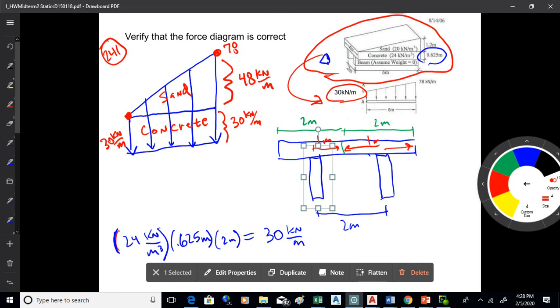I'm not going to do it on the first one, because what I want to get is these loads are somewhat instantaneous. So what I would do next would be to find what is the load per unit length of the sand at that point, and then you can assume there's a linear distribution as you work your way up. So you're going to run a very similar set of calcs like what I just did for the concrete, but you'll do it for the sand, and you're going to find it at an instantaneous sort of number right there.